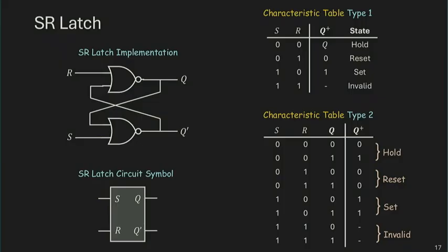You can also draw the same truth table with one additional variable by bringing Q from the output column into the input column. So this is really a device whose output, the next state Q plus, Q in the next execution run, depends not only on the current inputs S and R, but also on the previous output Q. So you can think of Q as an input, and put that in the input column of the truth table.